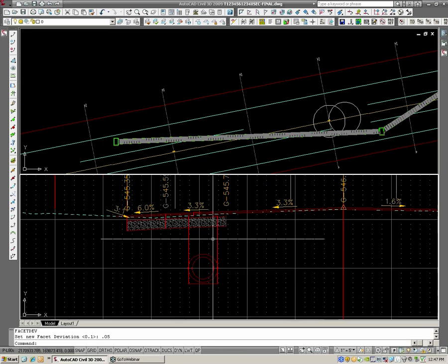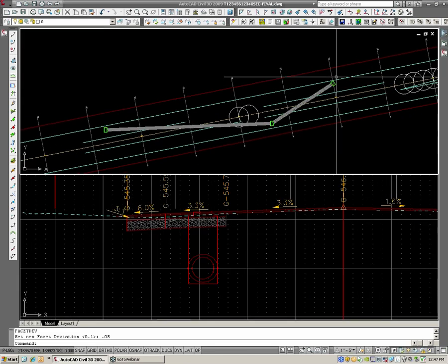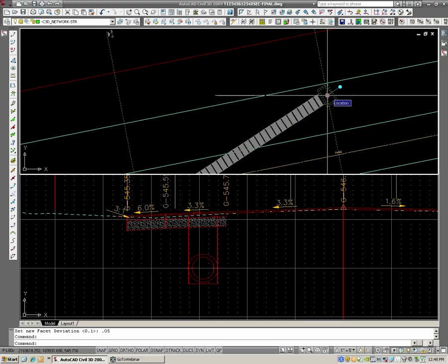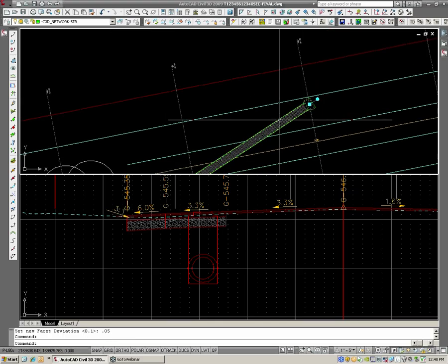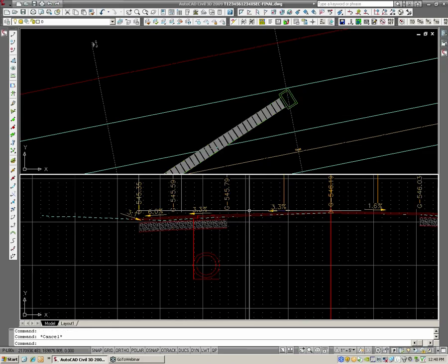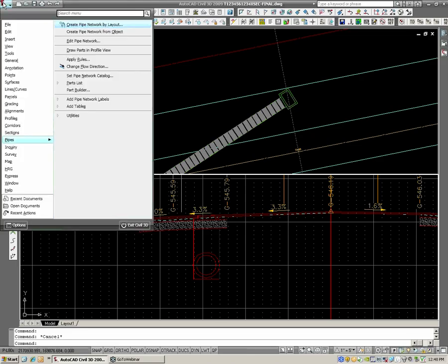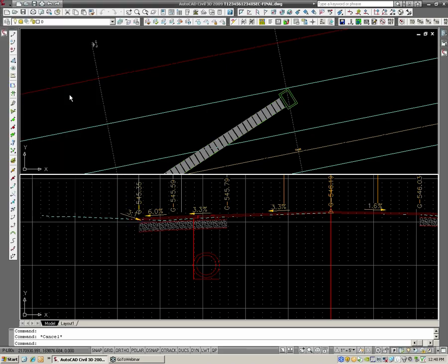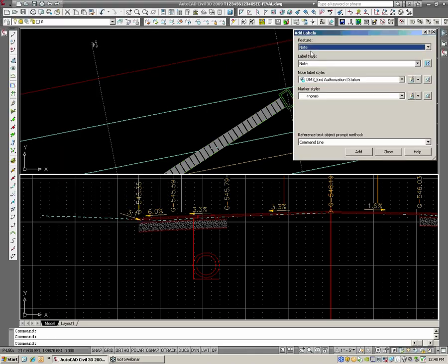And then here's my structure. Still learning a little bit. I'm trying to figure out how, if this structure doesn't lie exactly on the sample line, how it's supposed to show up. I think it's possible, but I still need to figure that out myself. But if it does fall right on it or any of those pipes, then it's just simply going up to general, add labels, and just like everything else, change this down to section view.